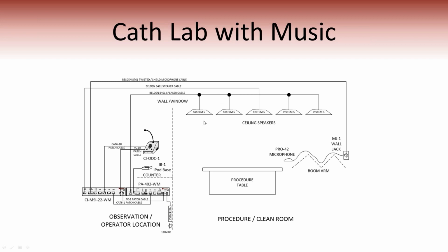The MSI has built-in phantom power. If I failed to mention that, it's got built-in phantom power, so everything you need for most microphones. I can tell you that Sennheiser and Crown require 48 volts, some of them, and that we cannot accommodate. We accommodate 24 volt DC phantom power. Again, you share a common power supply.